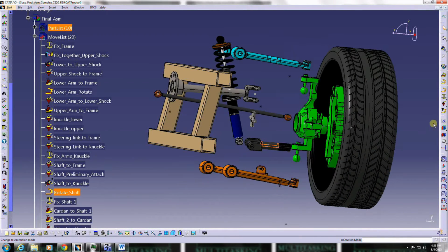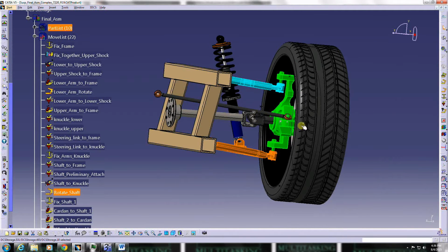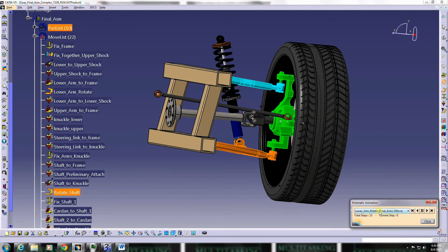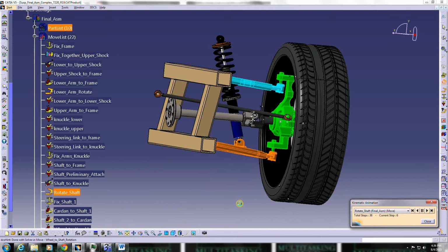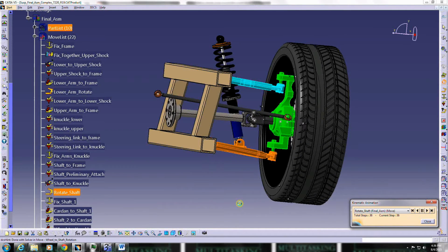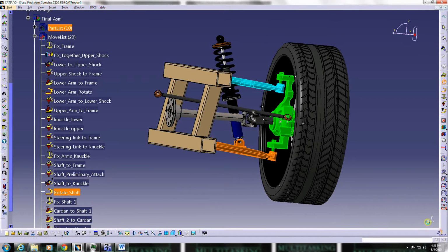It's saved without GD&T on, but you can also extract it in this as well. If you wanted to show any of the kinematic tools, what you'll notice is that you can only have 1 active motion move at a time. So here I've got to pick one of them to go through its steps. Similarly, if you were going to simulate it, you'd be able to analyze one at a time, or you could set both of these to a particular rotation and analyze that with a regular simulation.